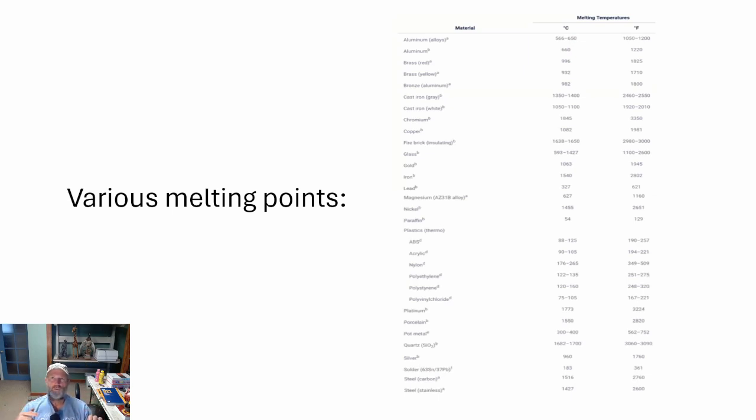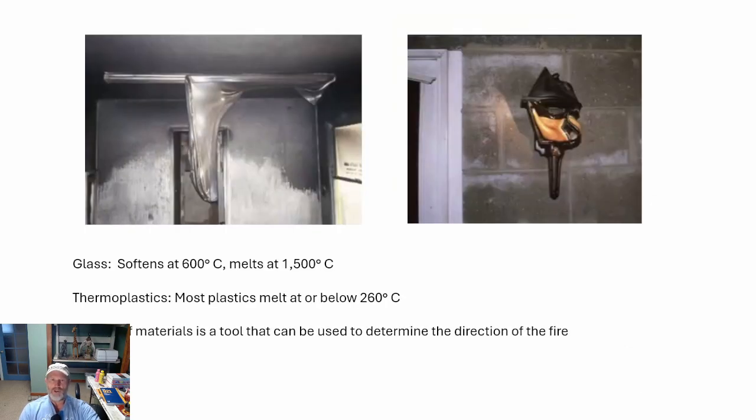Now, consider water, for instance. You can have frozen water, you can have melted water. They exist at the exact same temperature, 32 degrees Fahrenheit or 0 degrees Celsius. So they can coexist. Hence, a glass of water with ice cubes in it. Same principle. That doesn't necessarily exist like that for every material. There's not a clear, defined solid-melting temperature for some materials. There's a range for some materials. Thermoplastics are an example of that. And what you can see here demonstrates that.